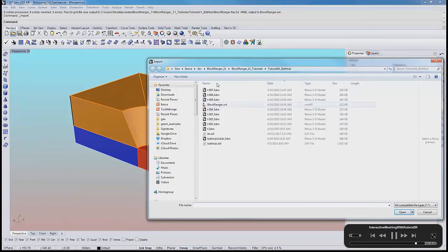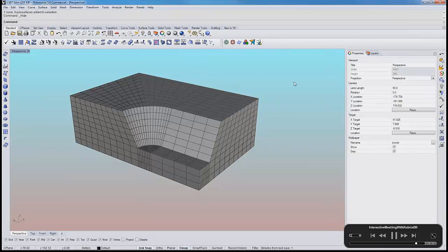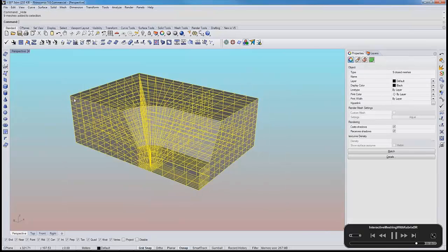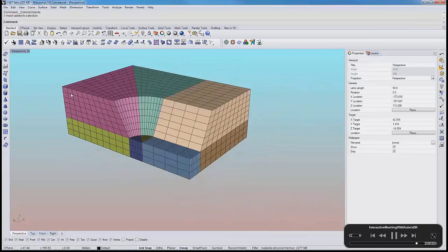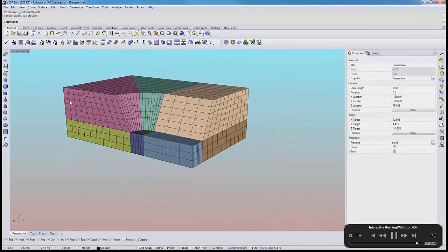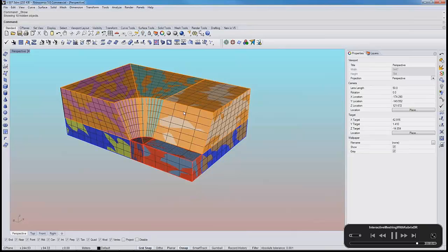In the property page of it, I set a number, which is the resolution that I would like to see for this particular edge. And now I look at the mesh and I see that the number of elements in this upper layer altogether has gone from 3 to 6, which is what I have, and of course it propagates throughout the whole mesh to go completely to the other side as well. Again, now I want to control this edge.